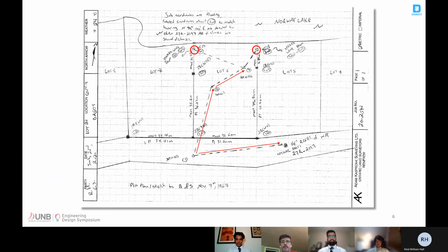While on the last station, point 4, we can see that 2 monuments were set along the property boundaries. Survey monuments that have been set are typically represented by a hollow square. Filled-in squares, such as highlighted here, denote survey monuments that have been found. This further enables a reader to quickly distinguish between monuments that have been set versus found.